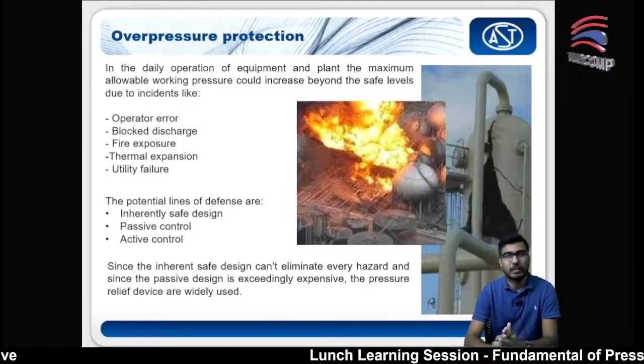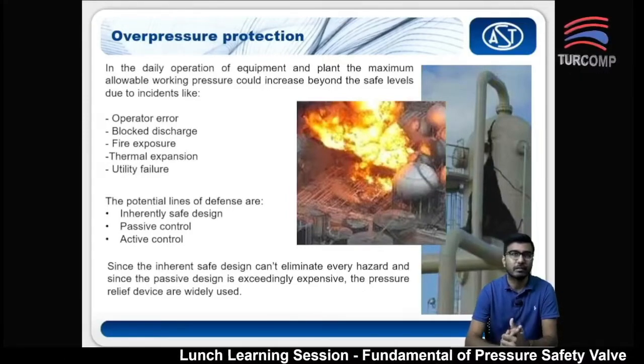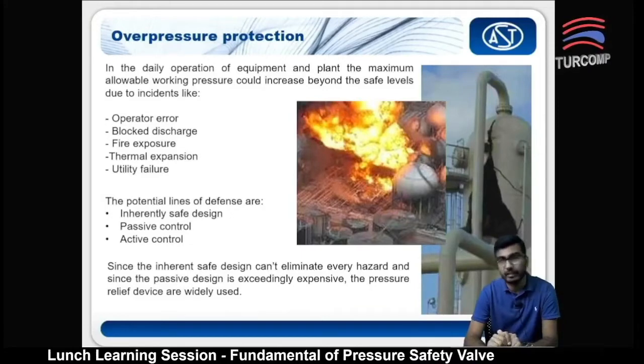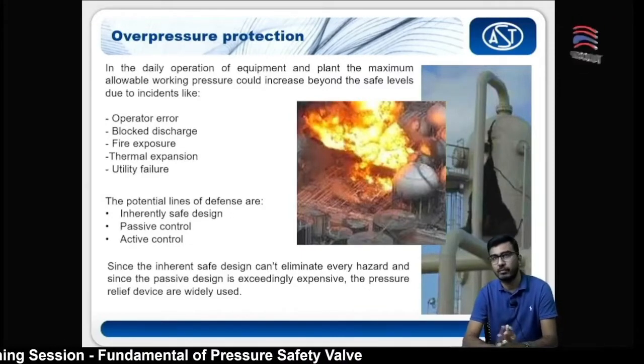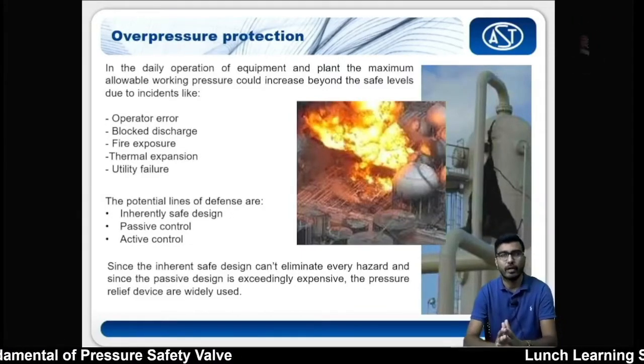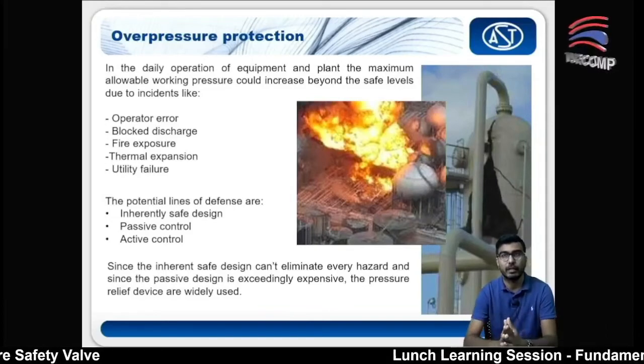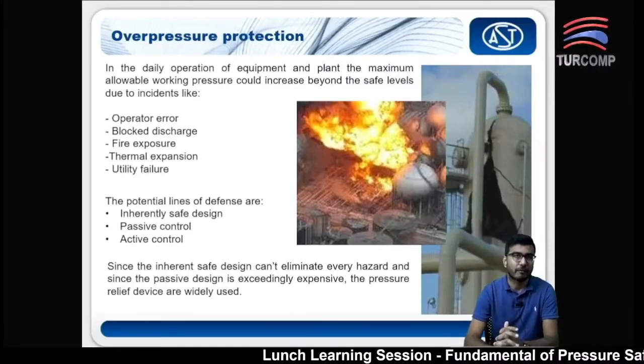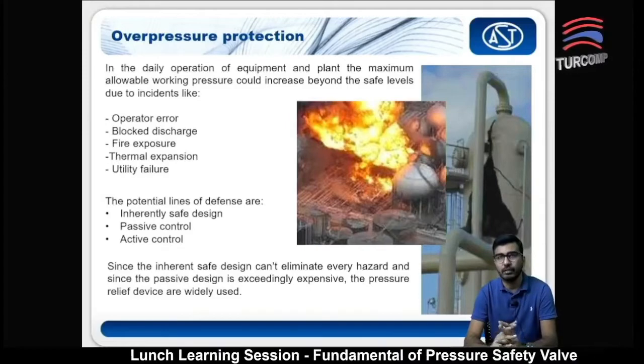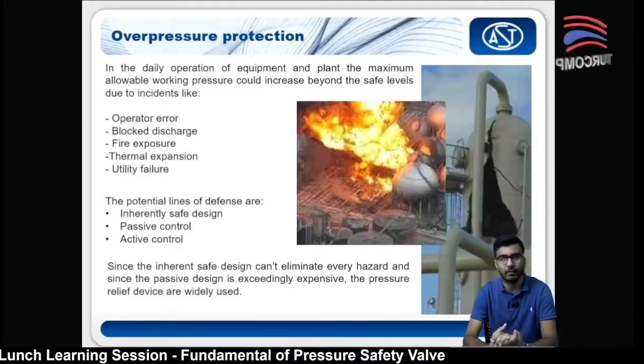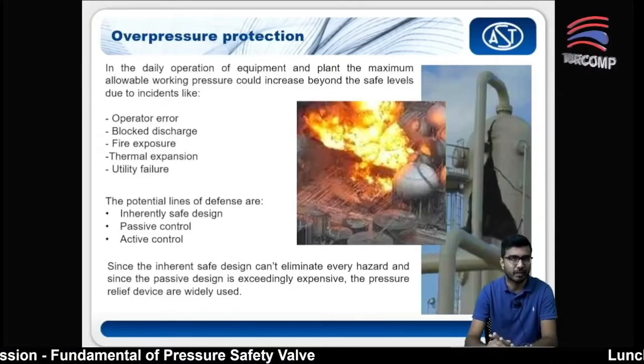So some of the incidents that can cause the overpressure would be operator error, blockage at some of the discharge pipe, where you have a pressure accumulation, fire exposure, utility failure. All of this is some of the incidents that can cause overpressure incidents in your plant.